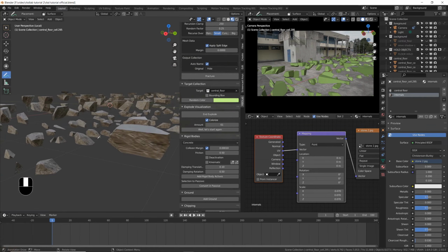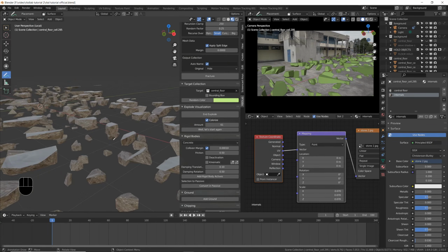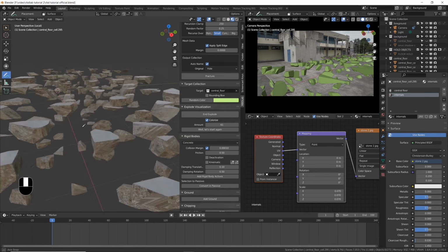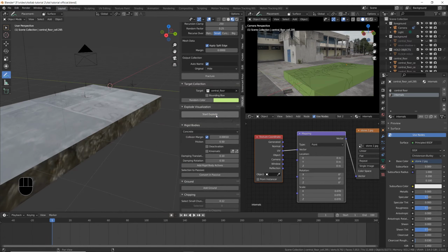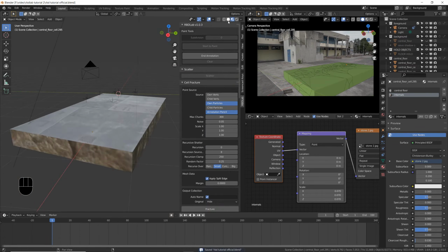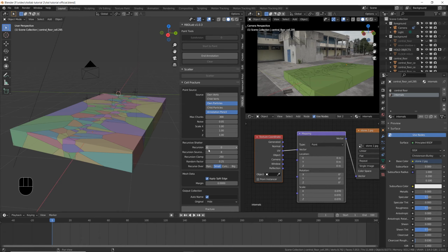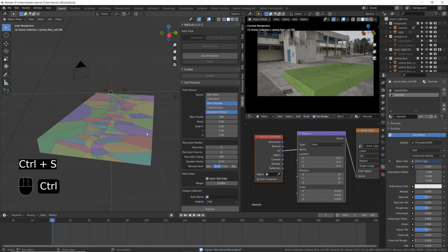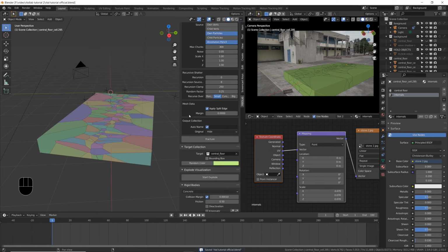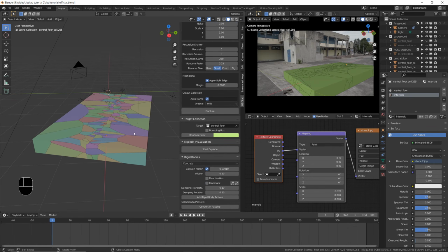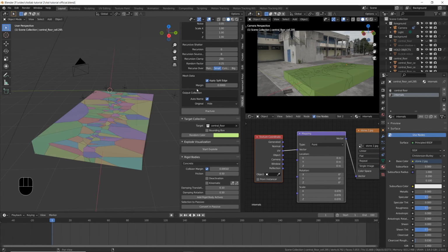So, we have fixed the faces. We don't have to worry much about this now. We can click on End Explode. We can go into Object Mode now, and we can transform everything into rigid bodies. The cool thing about this add-on is that you don't have to select anything, and you gain a lot of time because you don't have to select stuff every time you do something.